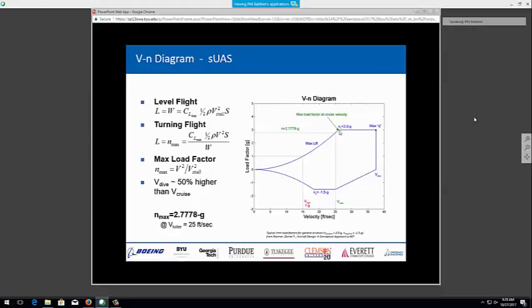Essentially, I created a model to get the amount of electrical input power necessary to give a pound of thrust, and that stays relatively constant across the sizes of motors. And then a thrust decay at 30 miles an hour, so we're getting a linear thrust decay with forward velocity. Those are just some very simple curve fits in this case.